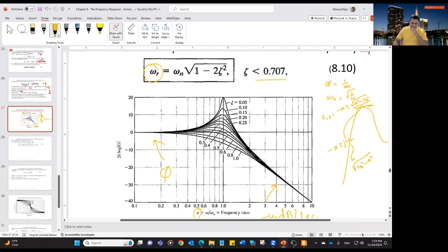So resonant frequency, in general, is the frequency at which your LC circuit tunes basically. So the reactance of L becomes equal to the reactance of C in a parallel RLC circuit. That frequency is the resonant frequency. And at that frequency, you get the peak value of the output, if we talk about circuits, that is.